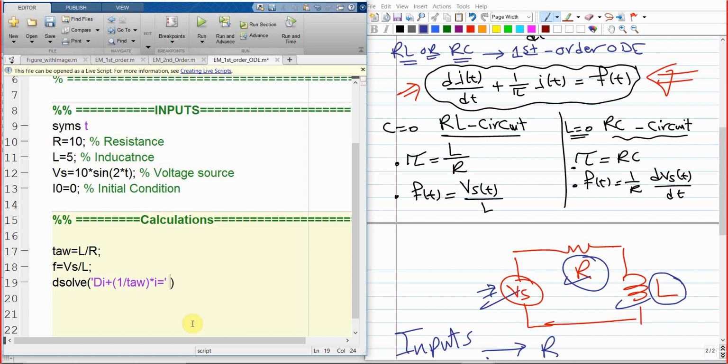Then you're just gonna have space and type the CHAR, which stands for character, and open two brackets and give the same variable that you already defined before for the F, which is F. This is the forcing term. So why didn't I type this F, for example? It should equal F according to this equation, right? This is acceptable as long as this F is a value, not a function.